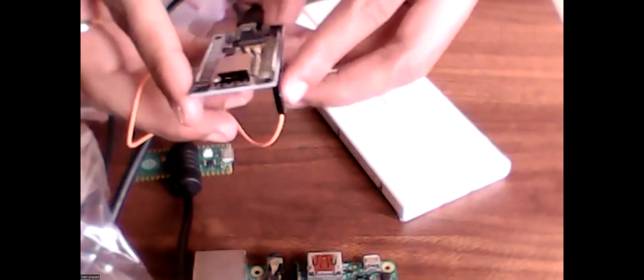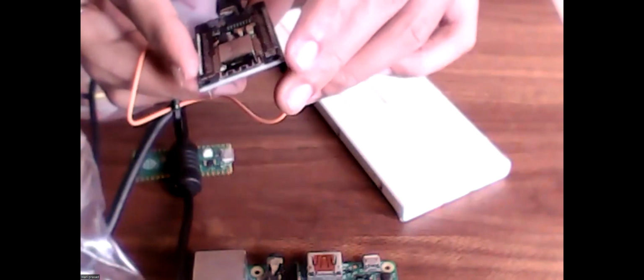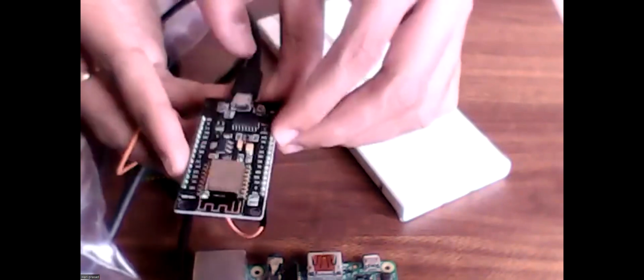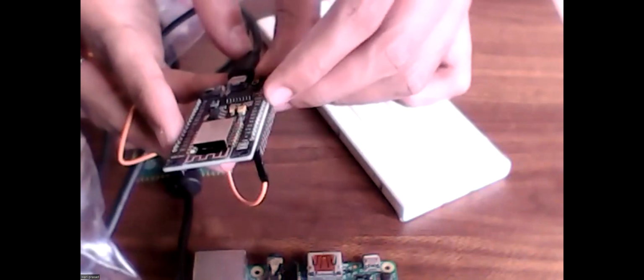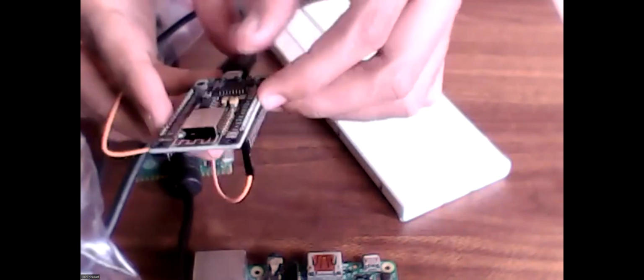So you can see here 3 volts. Sorry, we have 3 volts. This is actually not 5 volts. In Arduino usually it will be 5 volts. Here it is 3 volts. So yesterday's computation also we have to change actually. Because it's not 5 volts, right? So we have calculated with respect to 5 volts, but we have to calculate with respect to 3 volts. So there is one 3 volt pin also.